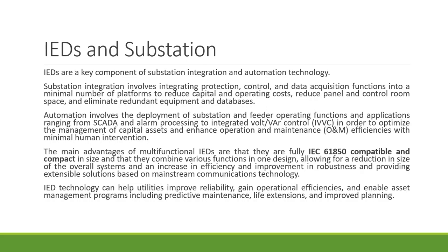We talked about the multifunctional IEDs that can be used. When multifunctional IEDs are used, they must be compatible with IEC 61850. We already discussed a little bit about what IEC 61850 is. It is a communication protocol, with interoperability with the communication network. That is required. So multifunctional IEDs are fully IEC 61850 compatible and compact in size, so that they combine various functions in one design.